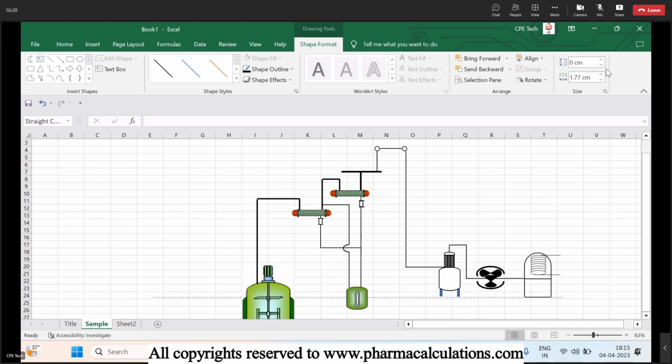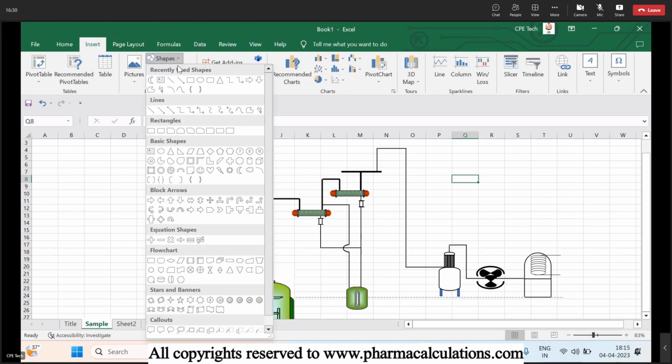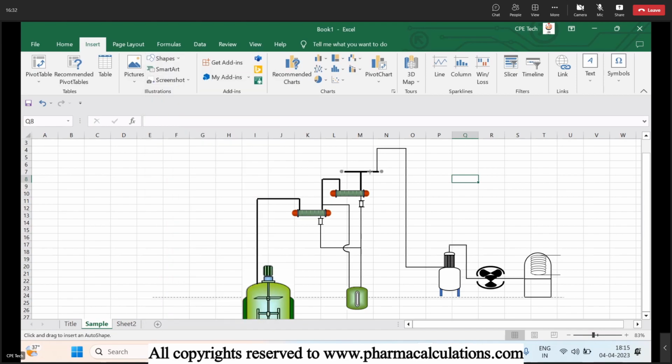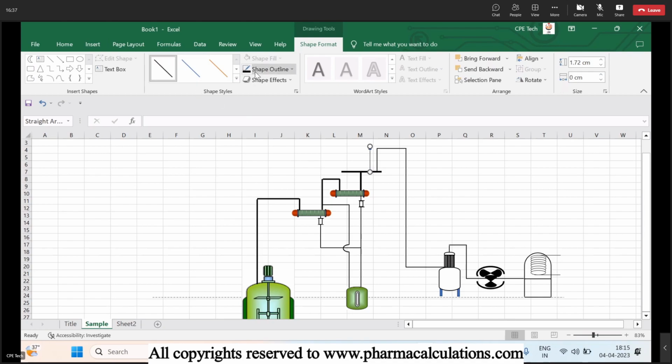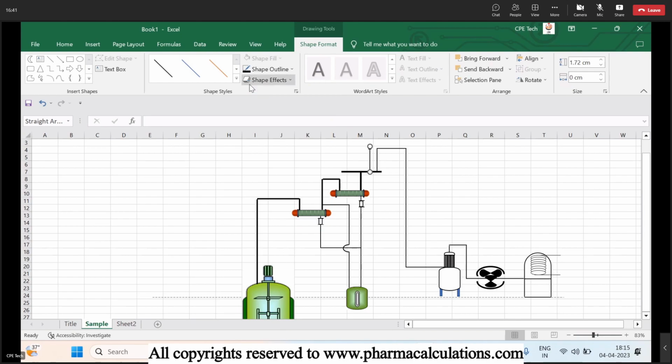And to this vacuum system we need to add certain valves and all, and apart from this, to this header we need to add a line like the general vent, and also we need to have some scrubber vent to scrub off any flue gases which are being generated, and there should be a line for a nitrogen inlet.